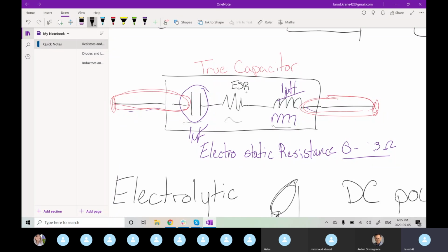These are on the range of milliohms to microohms. The values are typically so small that they can be neglected, because the added inductance of a capacitor is the same as just adding a little bit of extra wire in your system. So it's hard to truly keep track of, and it doesn't add a whole lot.